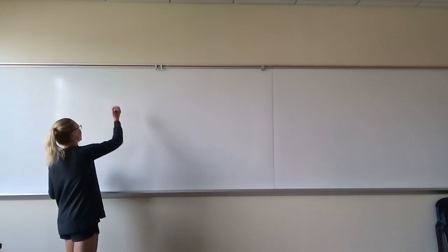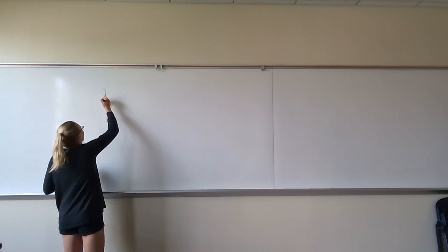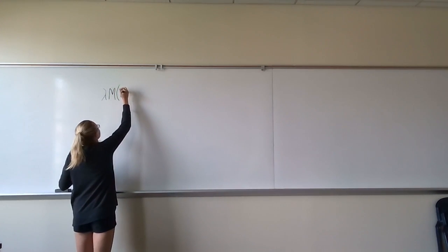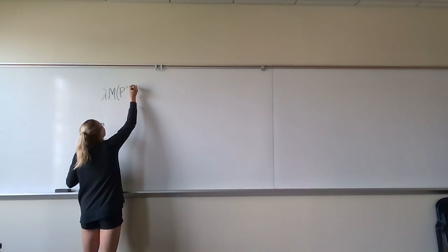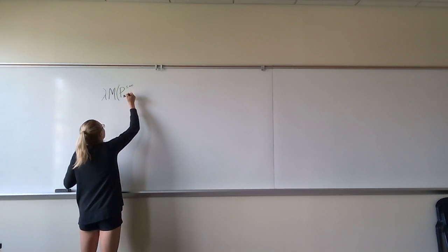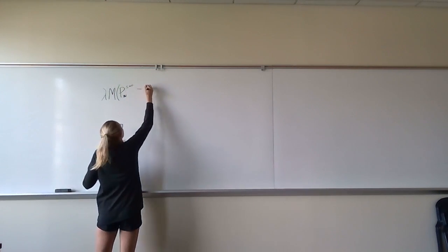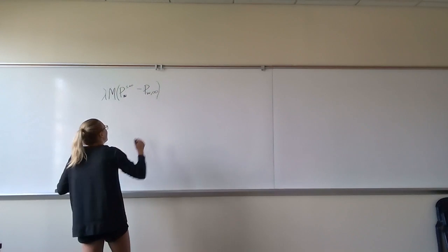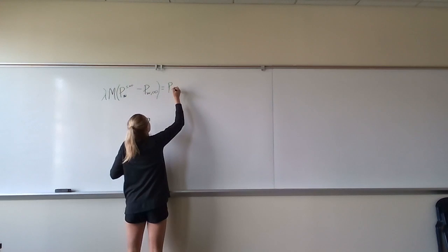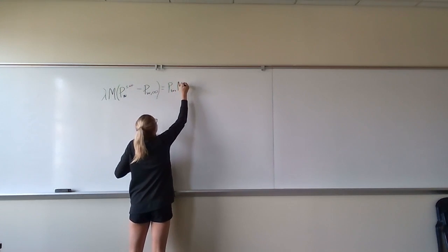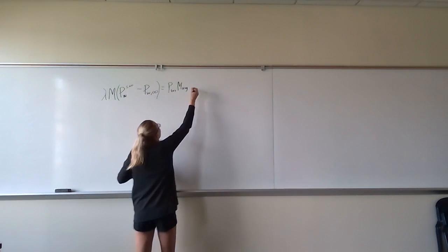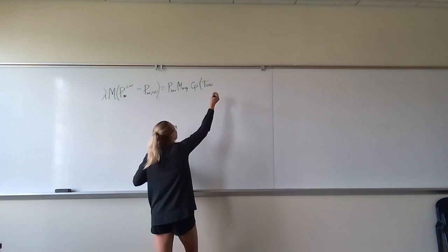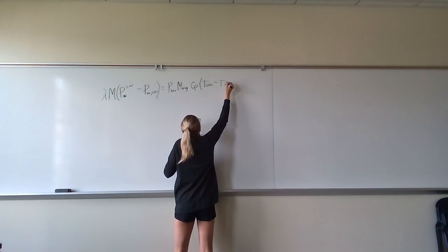So rewriting the equation from the last portion of the exam, we have the latent heat of vaporization times the molecular weight times the difference of the partial pressure of the saturated air and water vapor at the temperature of the water, minus the partial pressure of the water vapor far away from the surface of the wet bulb thermometer, is equal to the total pressure of the air and water mixture times the average molecular weight of the air and water mixture, times the heat capacity, times the difference of the temperature of the dry bulb thermometer minus the temperature of the wet bulb thermometer.